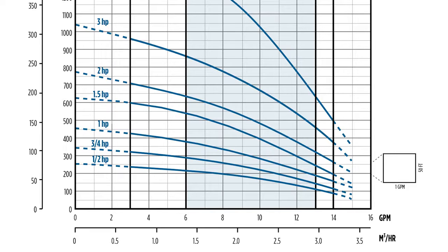Looking at the pump curves on a Tri-Seal 10 gallon a minute pump, we can see that a 3/4 horse pump falls short of performing to the level that we want. So we go to the 1-horse model, which will give us a little more performance than what we have specified. Whether we go with a 2-wire motor or 3-wire motor is optional.